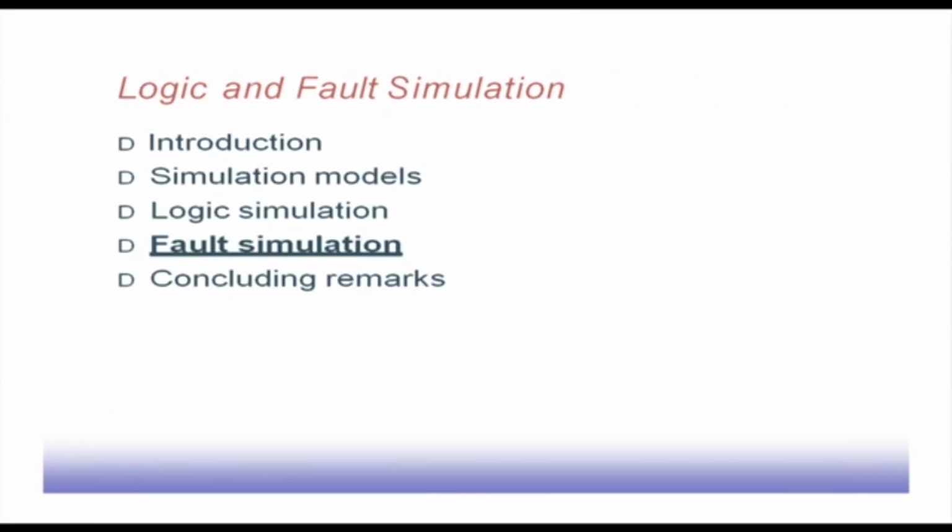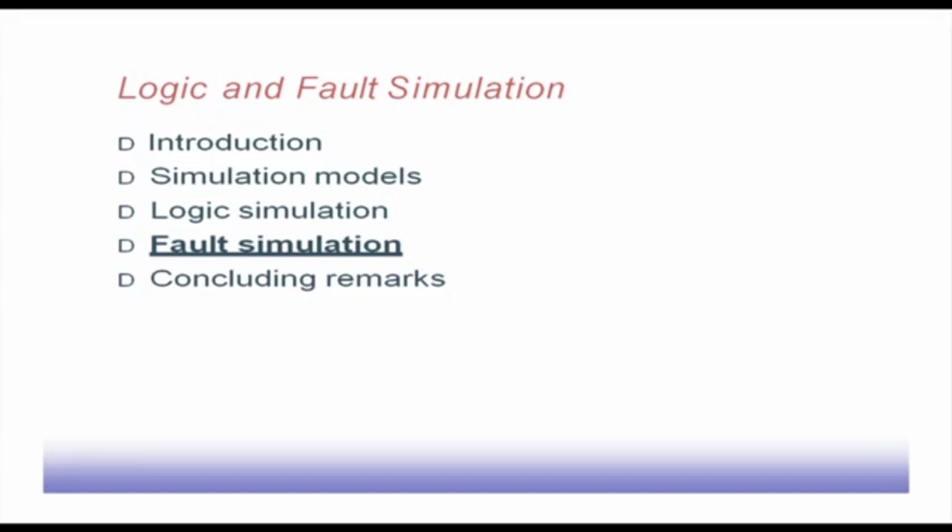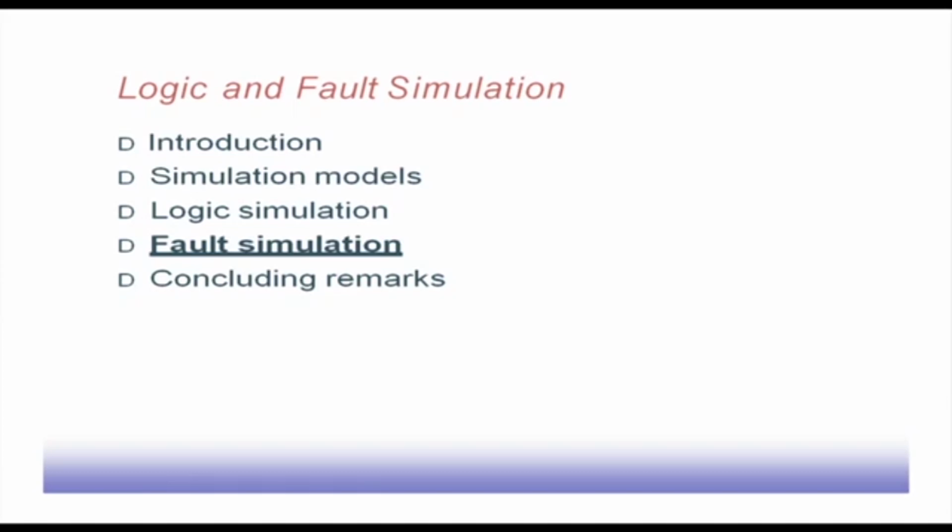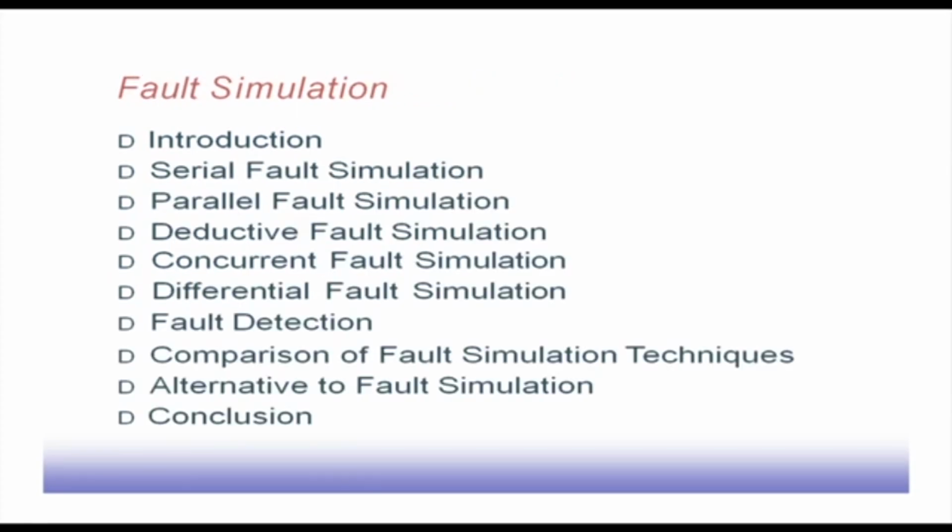Next, we will go towards fault simulation. Logic simulation is okay when we are doing it at logic level, evaluating the circuit, but under the existence of faults in the circuit we need to know what the output pattern is. If we get that information, we will check whether it is different from the good one or not, and if it is different from the good one, then definitely we have got the fault detected. So, this fault simulation will actually try to give a figure of merit to how good or bad a given test set is.